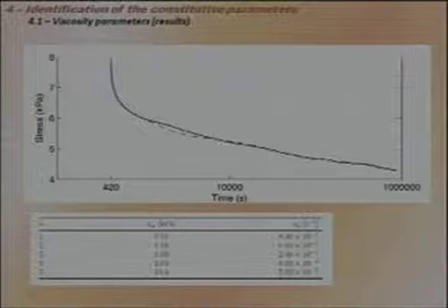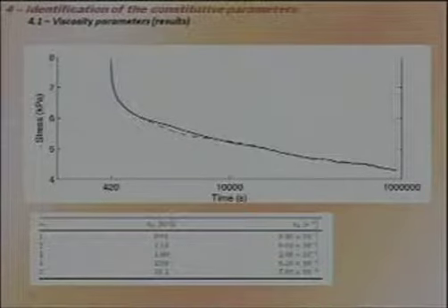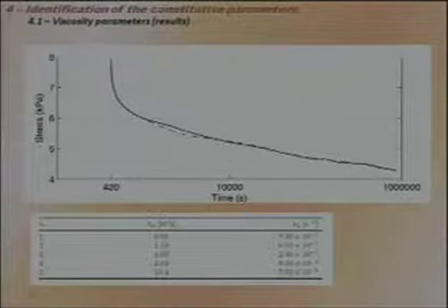We have the viscosity at the scale of one cycle, and we have the viscosity about the recovery of the properties when we leave the samples for 10 days or more. So we have a big range, and that's a difficulty too, and that's the reason we need 5 moduli of viscosity to describe the phenomena conveniently.